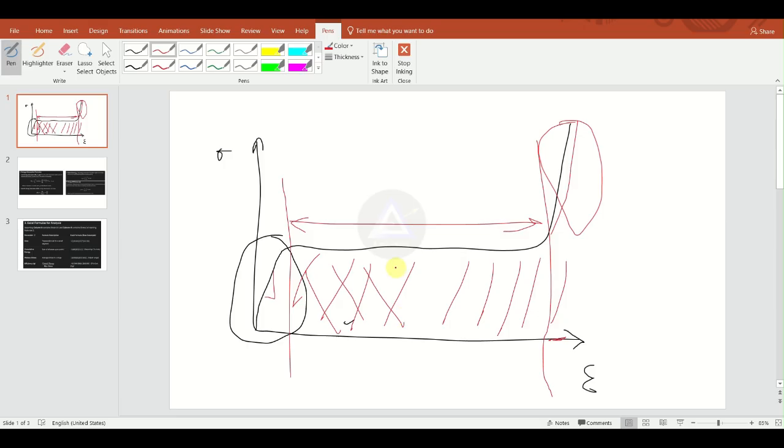It is up to you how you design your lattice structure, and accordingly this plateau region changes with the applied external loading. It defines the material's capability for energy absorption. This region must be higher so that the structure can absorb more energy. So you need to think in such a way when designing the unit cell architecture. These are the three regions we have.